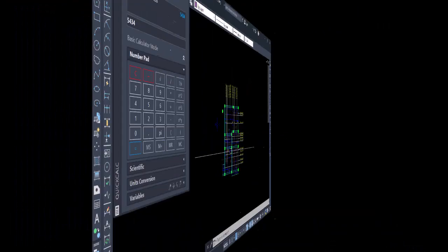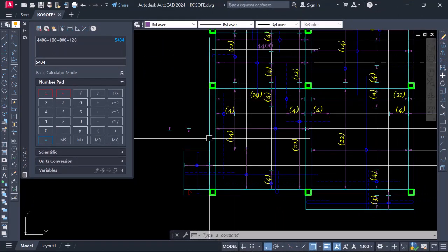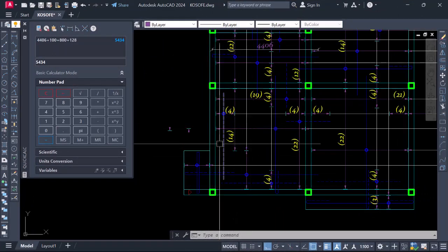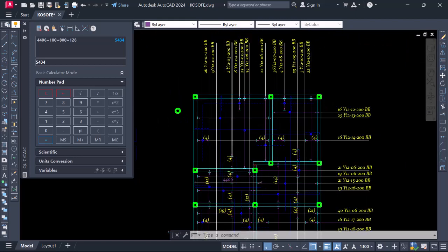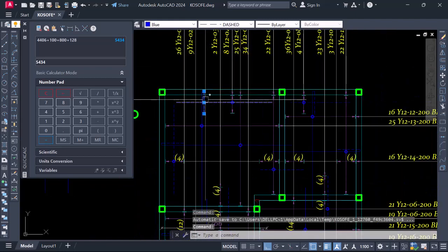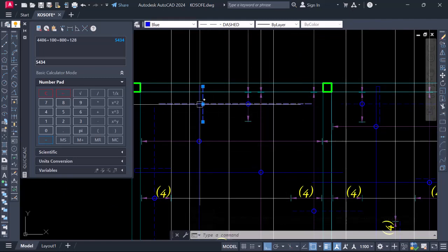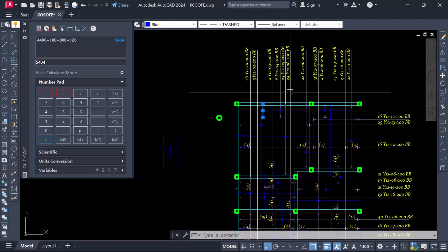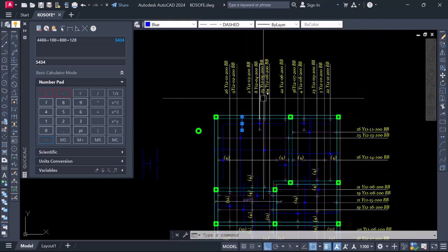All right. So when you have your reinforcement, what you're going to do is the direction. Now one has to be at the bottom and one has to be at the top, right? Because we have a mat. When you're matting, one has to be on top and one has to be on the bottom. So in this regard, this one, which is the shorter span, will be our main, and this is going to be on top of it. So we're going to tell one to be the bottom, and the other to be the top.